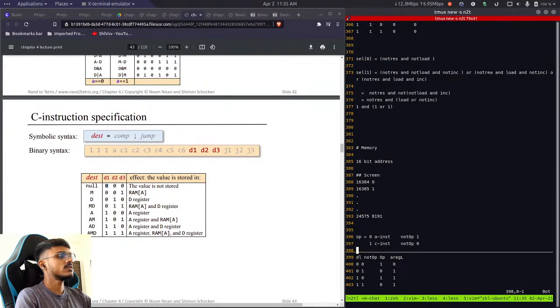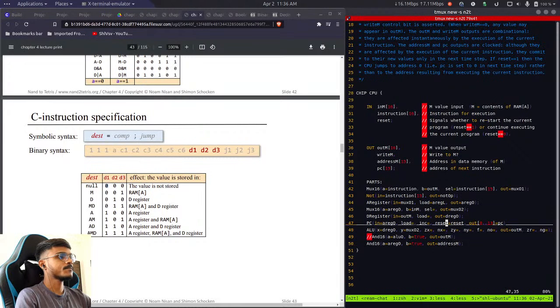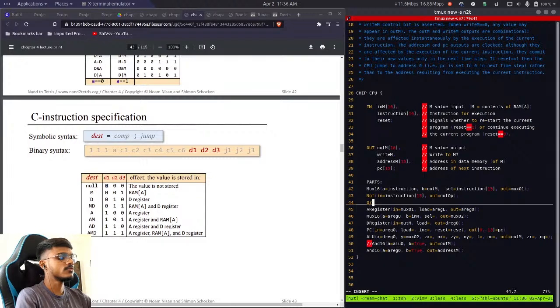So this is basically the truth table of a gate if we keep DL and not op. For 0 0 we will have 0 as the output. For all the other cases we will have 1. Oh wait, it is not AND, it is an OR gate. So if we keep not op value, we can just use an OR gate. So let's do that. I'm not going to get rid of not op, but I'm going to use an OR gate.